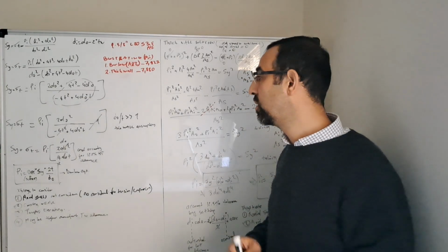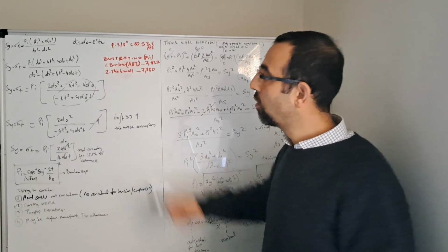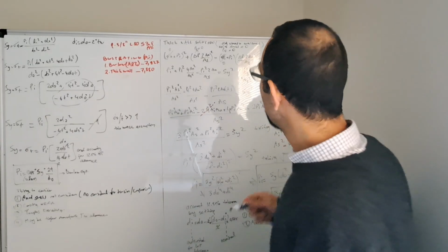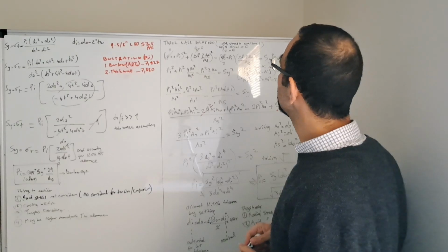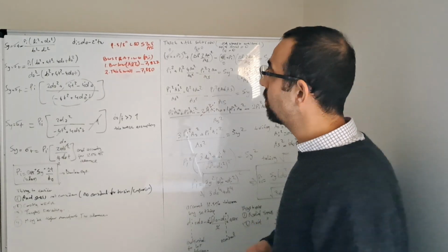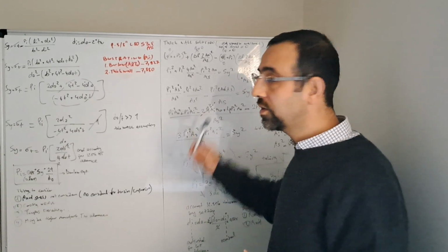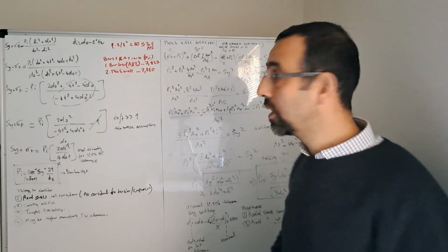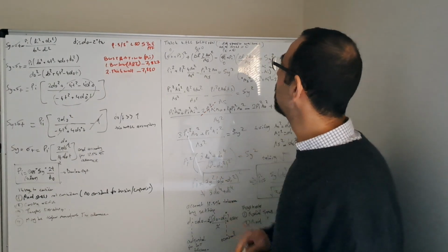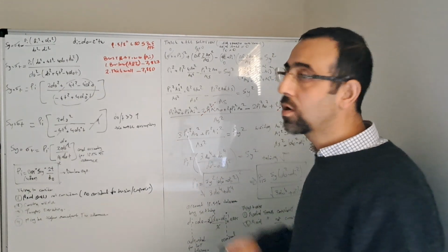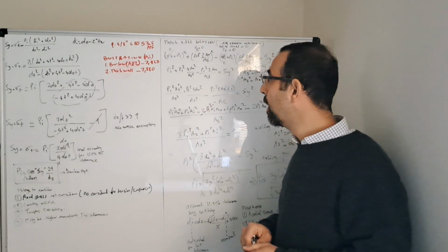Uniaxial limits are shown on the design limit originating from the Barlow equation. So on the right hand side, what I'm going to do is the thick wall solution. This time we will consider the radial stress. We will not neglect it, and I will still call the axial stress 0 because it's a uniaxial rating.